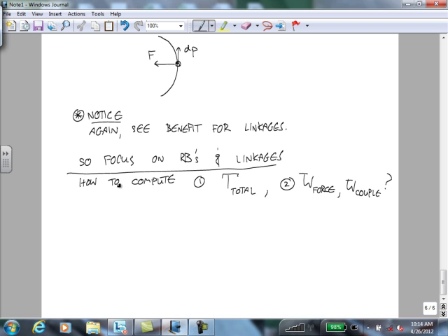we're going to see that the total kinetic energy and the total work is going to involve a bunch of variables, right? We're going to have omegas for all the different bodies. We're going to have F's for all the external loads. These are all variables we're going to have to solve for. And we only have one equation of motion.